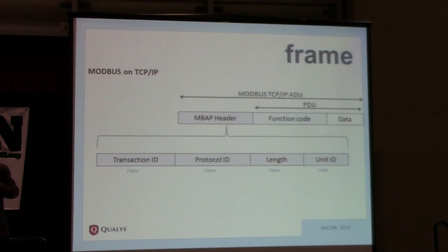When someone asks you a question, you say, okay, this is question number 1, this is question number 2, and that's exactly what a transaction ID is. Protocol ID is fixed for Modbus. Length is the length of the packet, and unit ID is something interesting, which is basically when the HMI asks